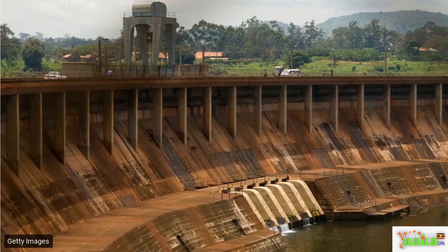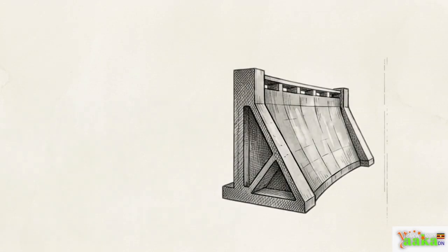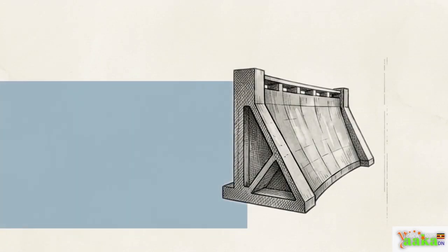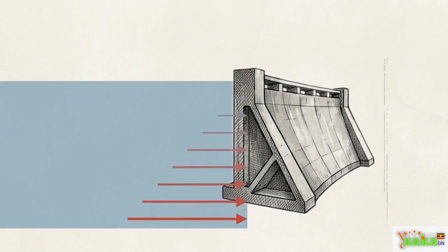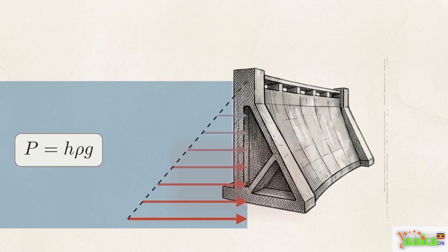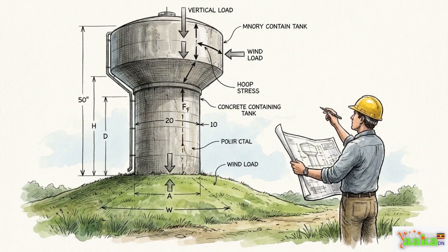These same principles of force and area govern the engineering of the Nalubale hydroelectric power station dam. Architects must account for pressure when designing structures that hold back millions of liters of water. As depth increases, the stacked water generates an outward force that concentrates against the lower dam wall. To counter this, the dam is built with a thickened concrete base, designed to safely absorb the highest concentration of force where pressure is greatest. Analyzing pressure allows us to predict how both localized objects and massive reservoirs will interact with the structures we build to contain them.